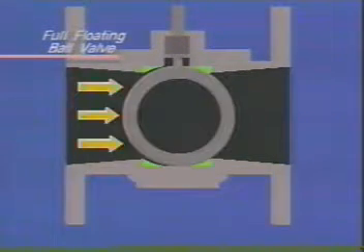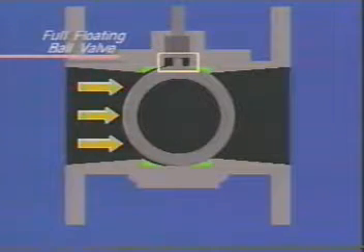The seat rings provide all of the support for the valve. When the valve closes, upstream pressure assists in forcing the ball against the downstream seat. However, to permit this, some backlash must exist between the ball and the actuator. The result is hysteresis, or a deadband, which can degrade the quality of control.